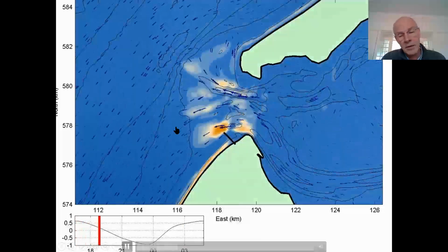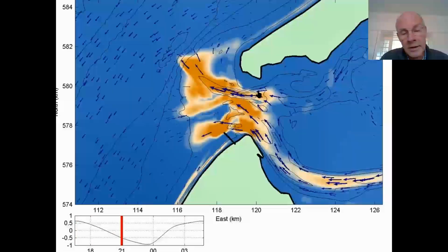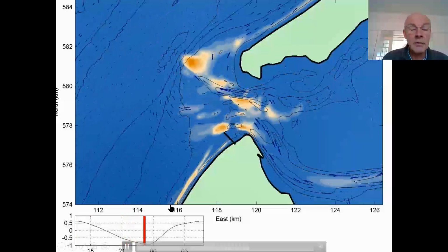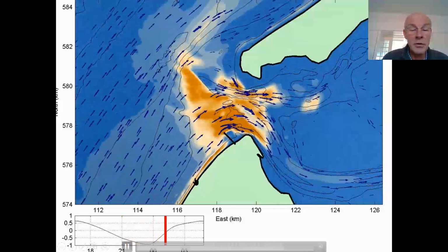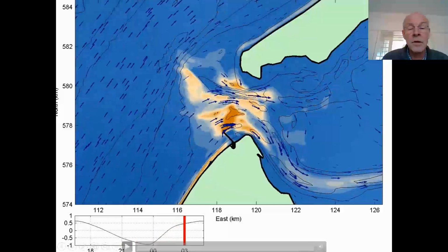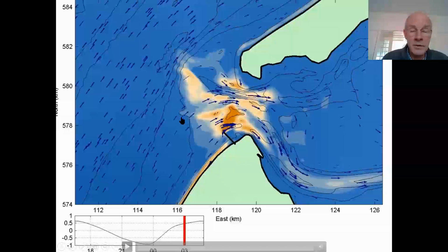And this then denotes the sediment transport pattern, where you notice high concentrations and transports along the coast due to the wave-driven longshore current, but also, of course, where you have major tidal currents, then there's a very dynamic area and high transports, and particularly also around this groin, this long dam, which is 400 meters long. That has a big impact on the current patterns and the transport.